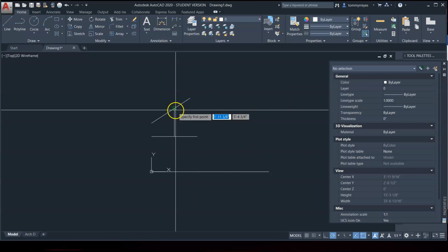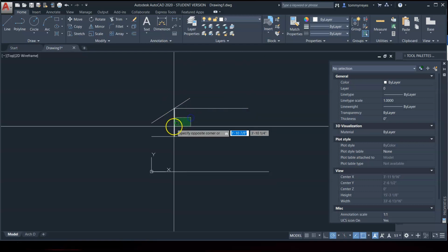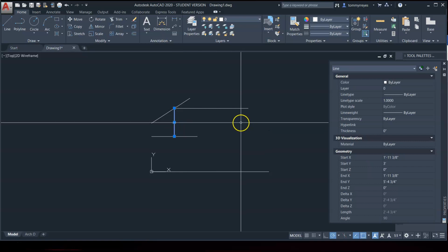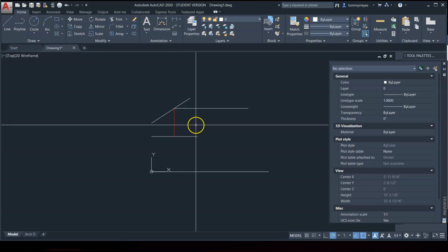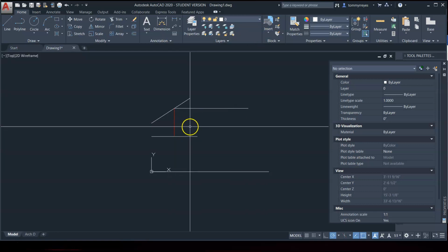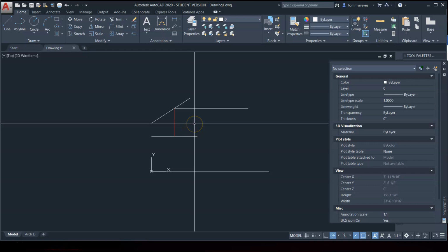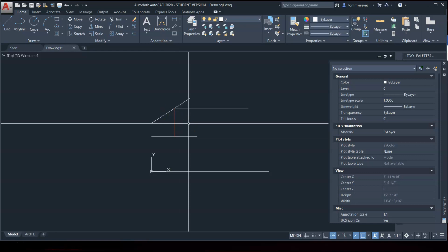And let's just say I needed other pieces of information, but I didn't need this. Or I need this, but I need to delete it later. I can change the color to give myself a visual of what I need to delete later. Typically, I make a layer, and I put every construction line that helps me draft on that layer, so I know to erase it later.